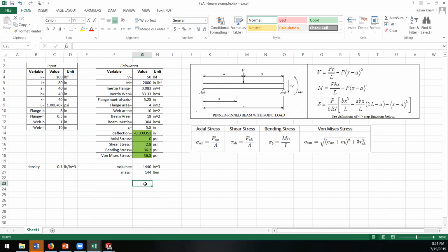So there's always a different solver, right? FEMAP is like the modeling, and we use Nastran to run it. They're synced, but sometimes you just export from FEMAP, then you open Nastran and import it and manually run it. And sometimes you don't even put it back in FEMAP. You just go look for your max displacement in a table.